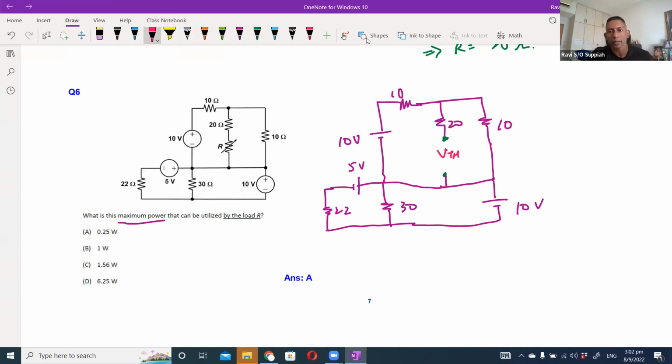Now, when I look at this circuit, if you look at this branch, even though it is a line that is shared between the upper circuit and lower circuit, there is no component here that causes any voltage drop. Because of that, we can treat the upper circuit and the lower circuit as two separate ones. We don't need to worry about any interference.